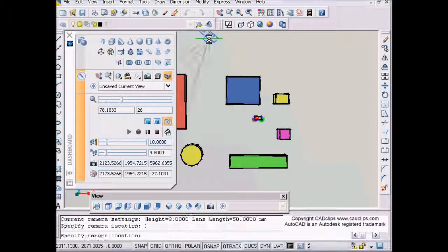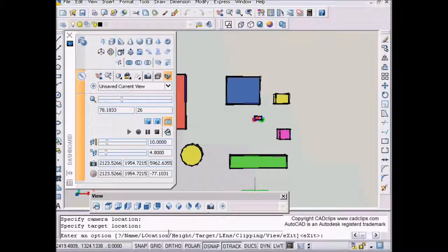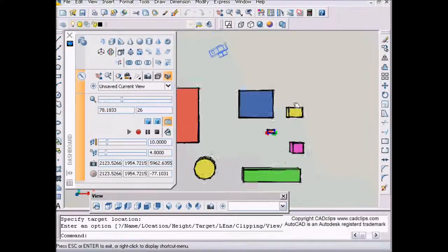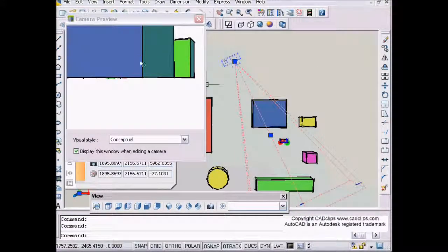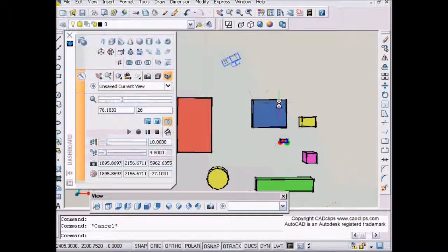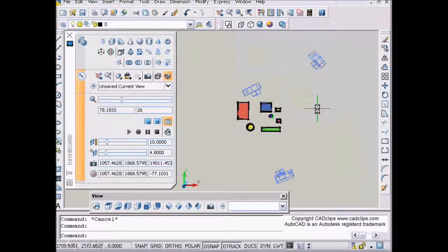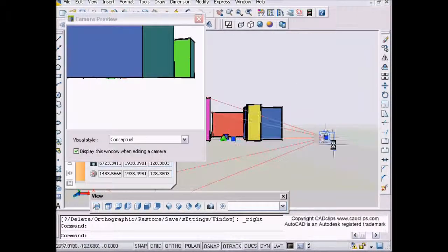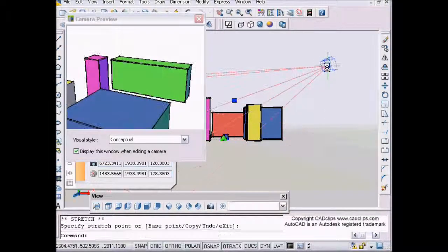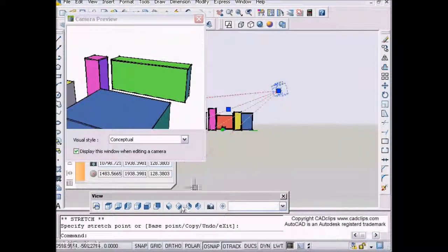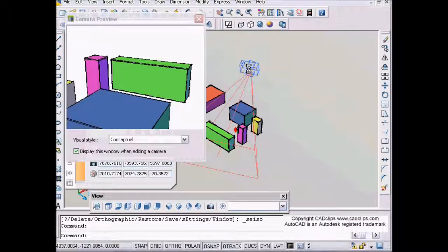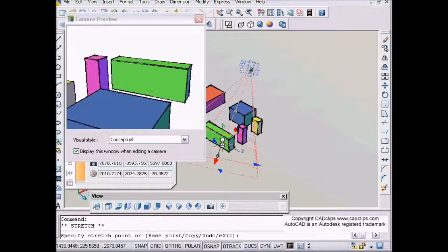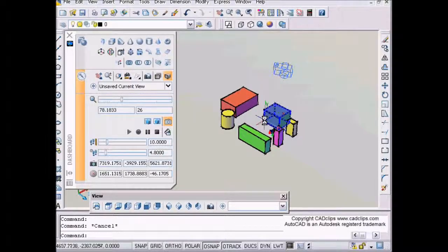Pretty straightforward. Pick the camera tool, pick a point, place it, and then have a look maybe at the help menu and set some more options. Basically, I just place it, and then after you set it, notice your Z, change your Zs, etc. You could also go in here and move the camera just by going into, for instance, my right hand side view. Okay, and I can grab that camera, and I can also move that camera up just by doing that, going into that view. Okay, going back to my 3D view, click in here, so off you go.